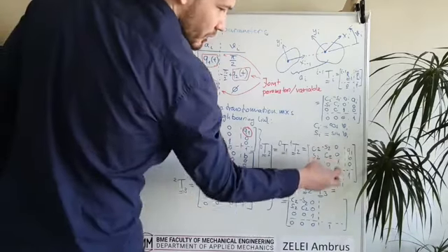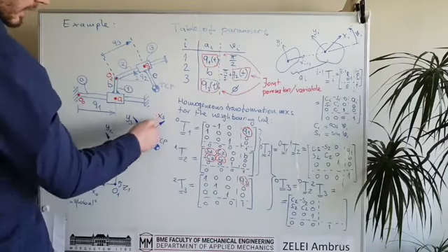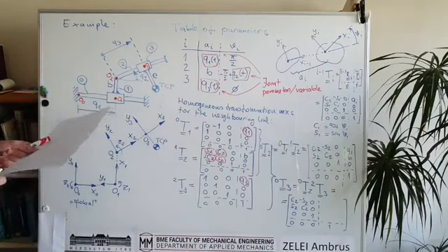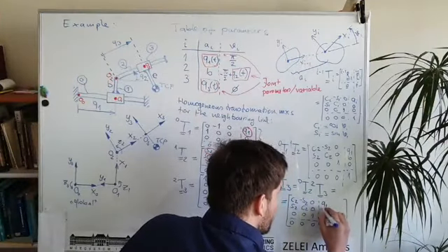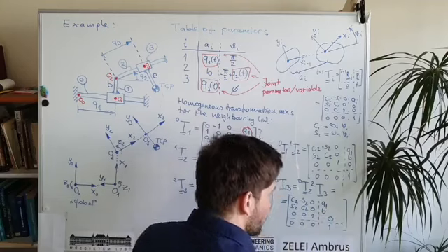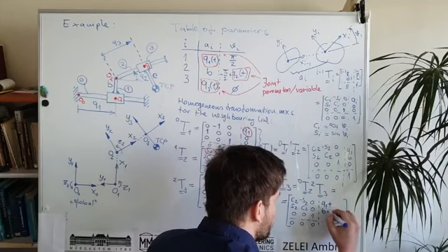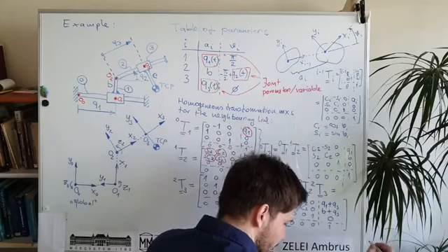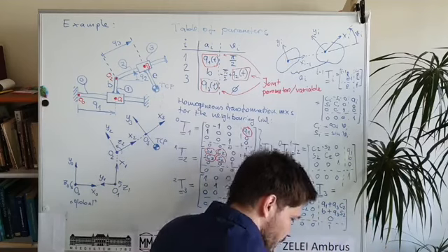So that's why the rotational part is exactly the same. But the translational part will be something different. So this will be q1, b, and it's always 0 in z. And additionally, we will have some new terms, q3 times cosine q2 and sine q2.